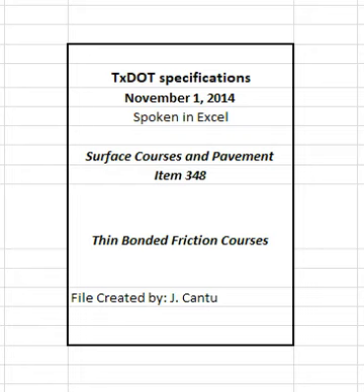Procedures for reporting job control test results, and procedures to avoid segregation and drain down in the silo. 4.3.4 Loading and transporting. For loading and transporting, include type and application method for release agents, and truck loading procedures to avoid segregation.